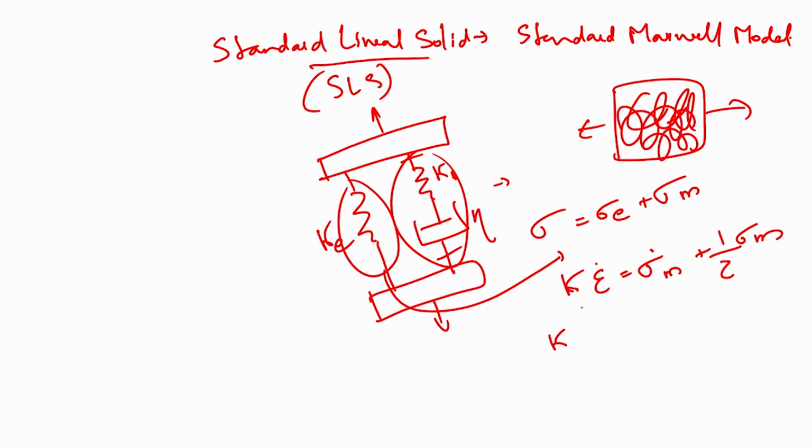So here this was the constitutive equation, and now in this specific case, the right side branch with the spring and dashpot in series, we can say the stiffness is K1. When we take the Laplace of the change in stress and strain, we get s times the change in strain, where the dash over the strain rate shows the Laplace transform of that same function.